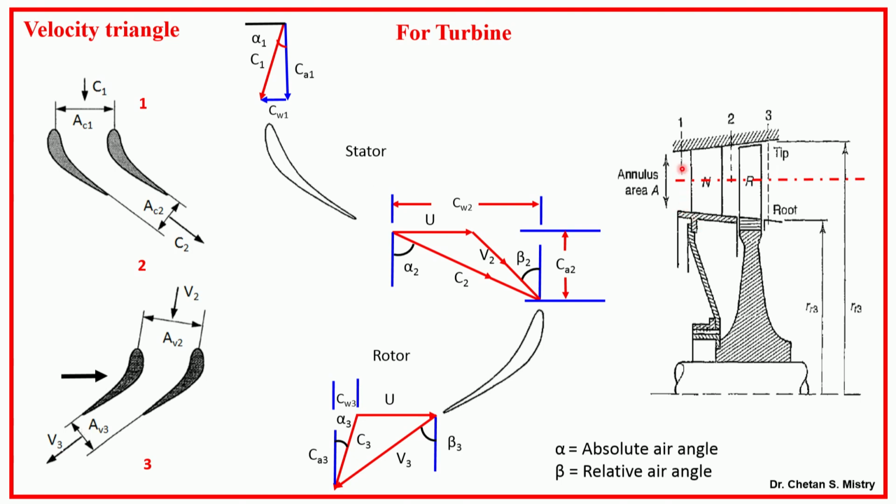Now, what is happening? We have our nozzle, which has a span from hub to shroud. In the same way we have the rotor, which has a span from hub to shroud. So, along the span we will be having variation in radius. So, when your radius is varying, your peripheral speed is varying. So, the component of peripheral speed u is varying. When u is varying, your axial velocity is constant, and your blade angle will be varying all the way from hub to shroud.